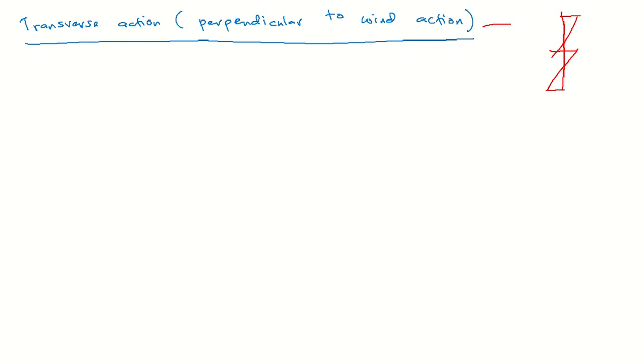For a frame we get the moment for the column; for shear wall, we will get the moment for shear wall. Okay, and to get just the moment, we use the third method, which is a simplified subframe at a point. Okay, so we are going to adopt that technique, simplified subframe at a point, or one point subframe method, the name of the method.